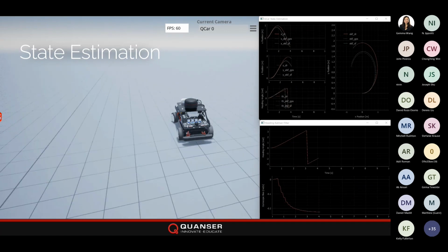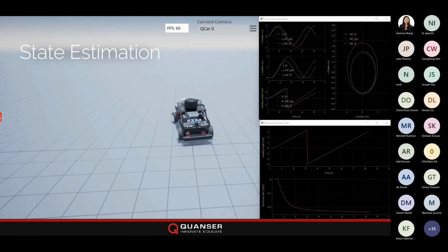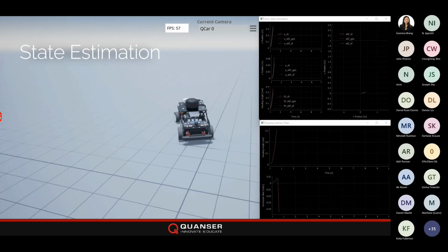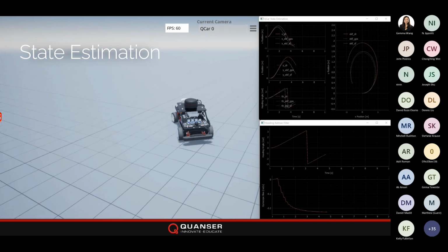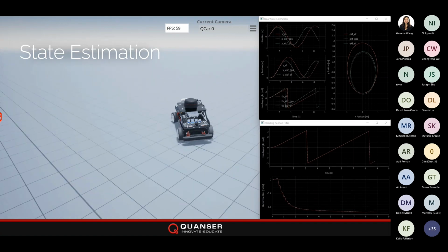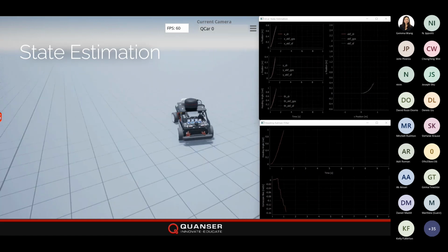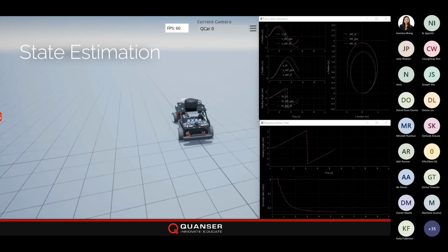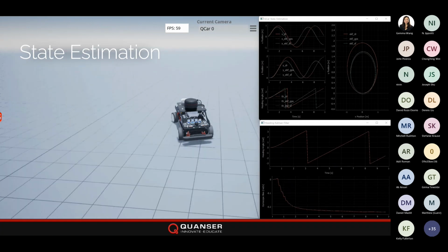We have an extended Kalman filter that's just based on the GPS. And then we have a more complicated cascaded EKF estimator, which is fusing together gyroscope data and GPS and the encoder and all these things. So you get to look at the effect of adding more information, and the role that sensor fusion can play, as well as the specific technical details of how to actually do it.